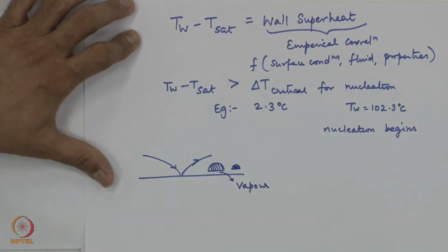I am sure all of us have seen this, may not have noticed it with that much intent, but when you try making dosa next time, if your batter doesn't spread, it is because the moisture in the batter, the water, evaporates and forms a cushion of vapor which prevents us from spreading the batter. That is why he splashes water on it, and once he splashes, the wall temperature reduces, he uses a cloth to clean up so that the temperature is made uniform, and then he pours the batter. This very fundamental aspect is so important in boiling: